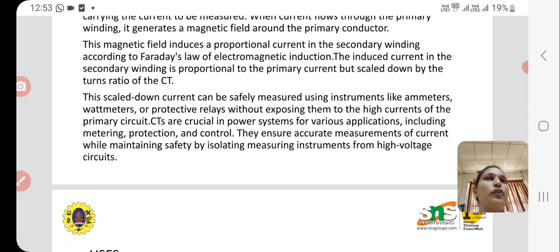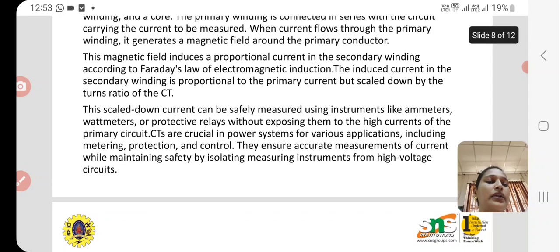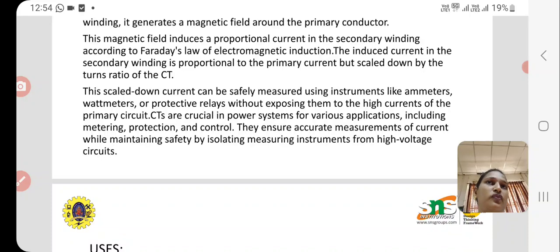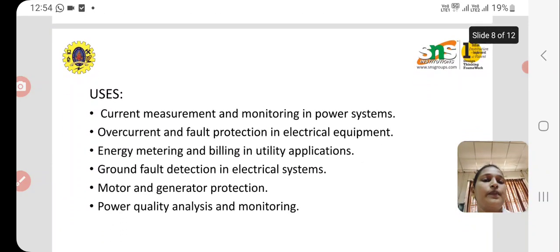We have certain types of ammeters which measure a high range of currents, but for very high values we don't have accurate meters, so we need to step down those values. For that we use CTs and PTs. CTs and PTs are instrument transformers, and they also give isolation from the primary high power circuit to the measuring circuit.